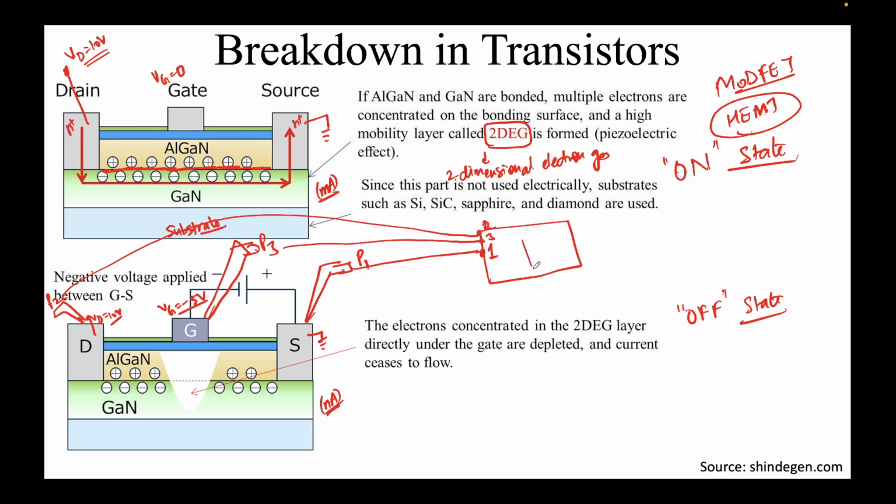And here there is a software user interface, where I can control what voltage to give to 1, what voltage to give to 3, and what voltage to give to 2. And I can also measure the currents, and this gives the data in terms of an Excel sheet, V versus I, and there are various other things that you can play with. So essentially that's how I'm probing, and you can see that I am using three terminals, which naturally are gate, source, and drain. These are the three terminals which I'm probing.